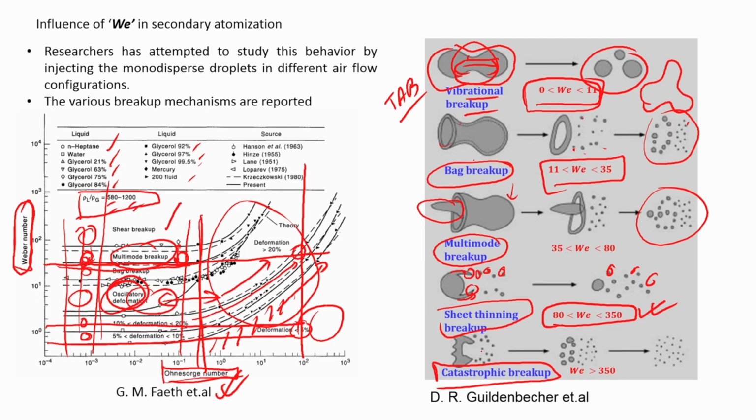The breakup is so violent that there is no fixed pattern in that, unlike this one, which has a particular sequence of events. First it inflates, then there is this protruding ligament, and then it breaks up, okay. Here it first thins along the sides and then the side starts to atomize. So, there is a process, there is a certain time sequence history, right.